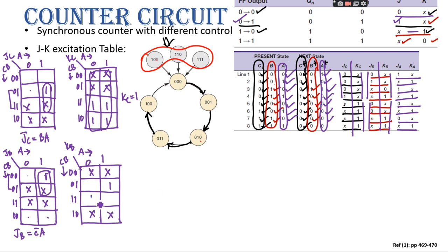So how can we do that? Lower 4 and column 1 4. So we can take these 4 as a group and these 4 as a group, right? Yes, sir. So my KB should be, if we take these two common, C, and here it should be nothing, so it should be C plus A. If you take this 4 common, it should be A, right? Yes, sir.